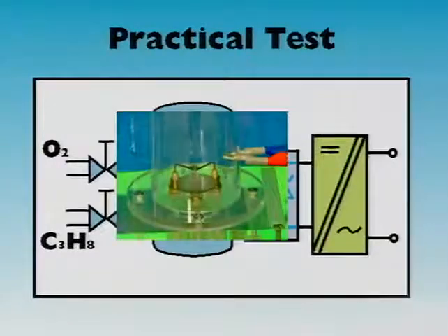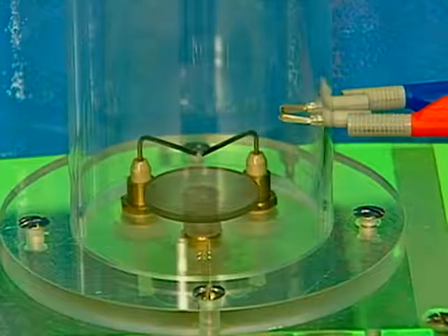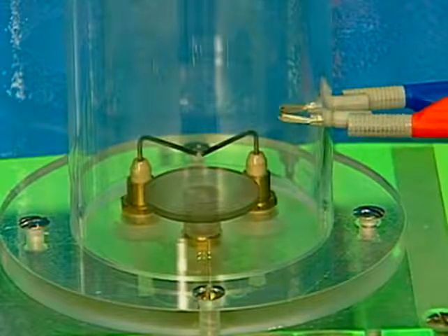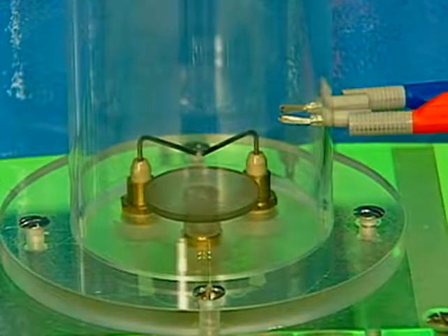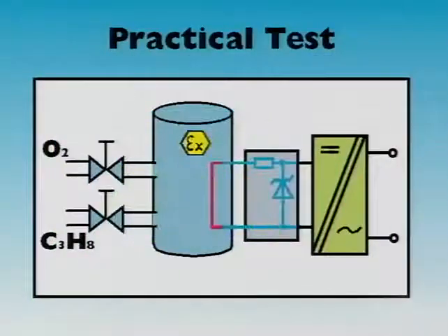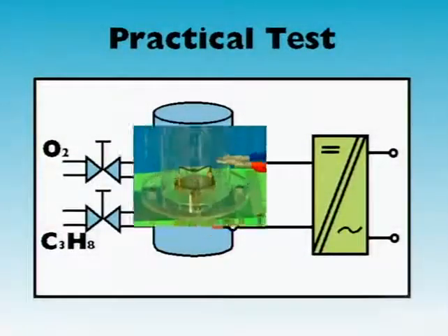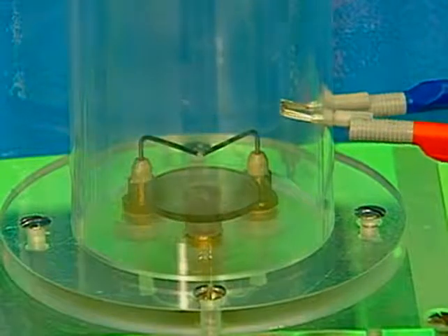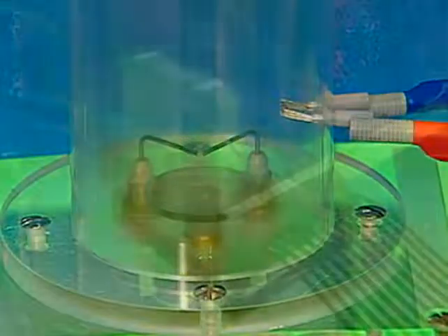We test the worst case once more and short-circuit the leads. A spark is created, is however unable to ignite the explosive air-gas mixture. The ignition energy is too weak. The reverse test. The secondary X protection is removed. The spark that is now created ignites the air-gas mixture and causes an explosion.